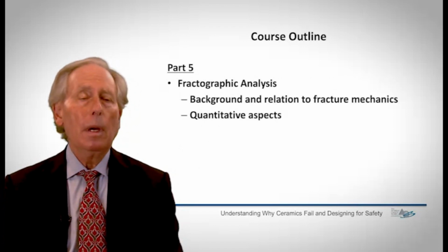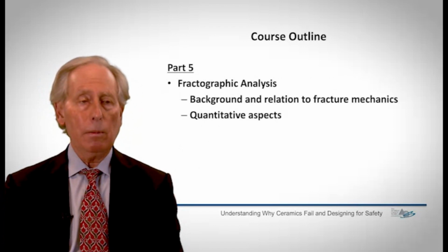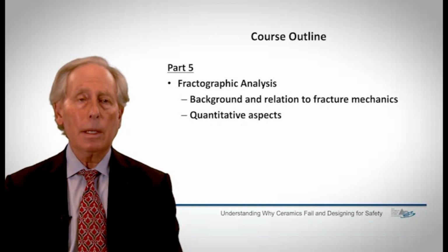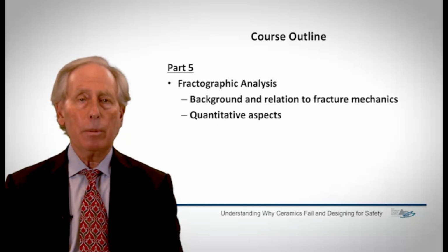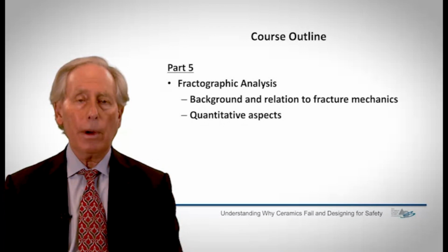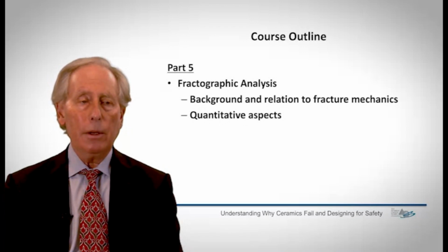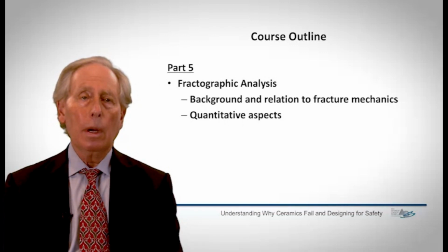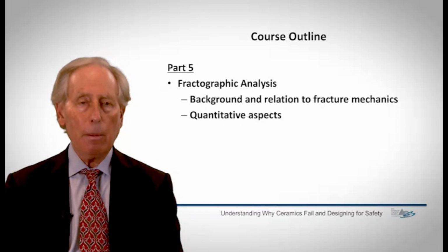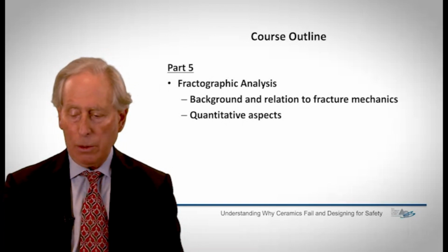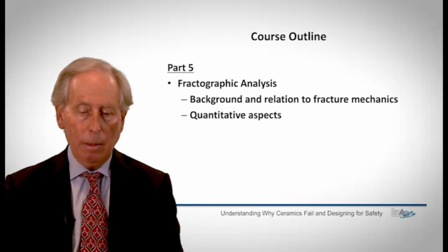Part 5 is on fractographic analysis, and the word fractographic means when a material breaks, there's a particular pattern produced on the fracture surface of the material, and there's a great deal of information about why the material broke, from what it broke, and maybe more important, at what stress it broke. So we can understand that by looking at the patterns on the fracture surface, and I'll talk some about how we go about doing this.